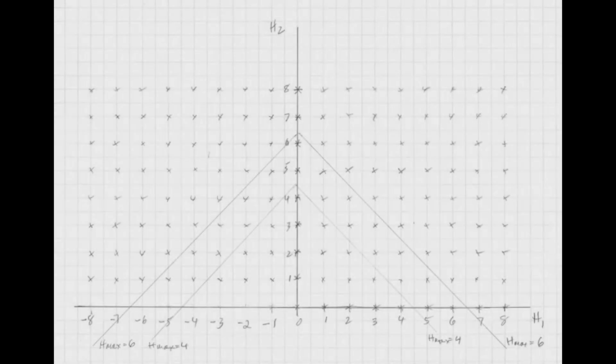Now, the next item on our list of essential things to deal with in setting up a harmonic balance analysis is the frequency set. If you have a single tone problem, let's say you're analyzing an LNA and you want to see where it goes into saturation and you don't expect to carry the analysis past light saturation, a relatively small number of harmonics is fine.